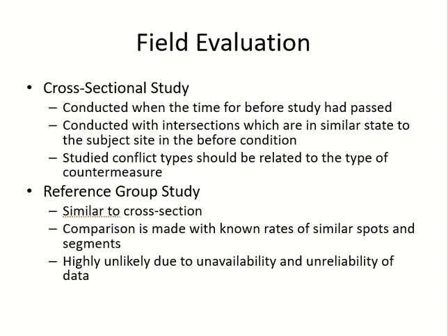So what is a reference group? The pool of sites we have. For example, I have a 4-leg intersection with a signal. So I will collect data from all 4-leg intersections with a signal. This will become my reference group. In this group, I have one site, my own site. Now I will compare my site with the average of the group. If it is higher, then we will consider that we have a problem. Otherwise, no.